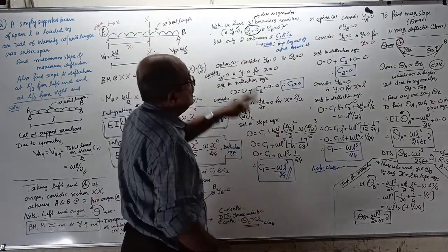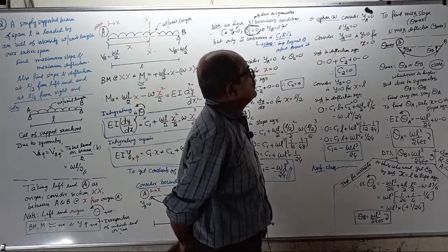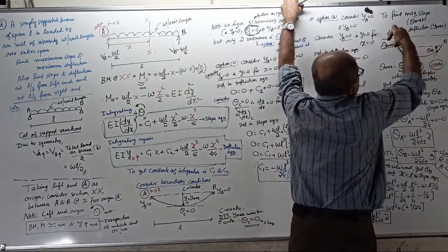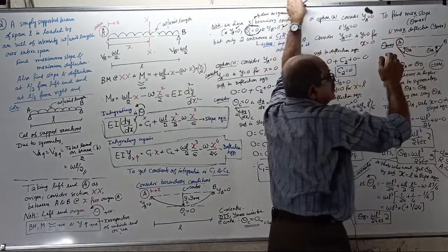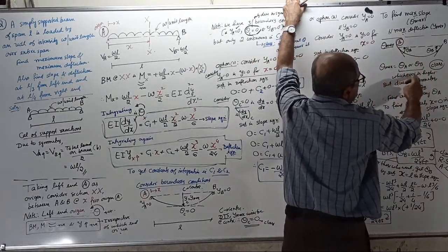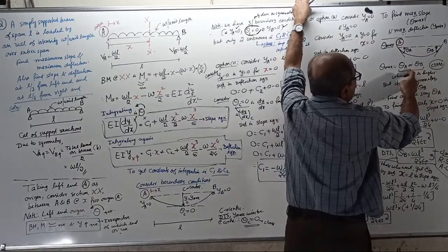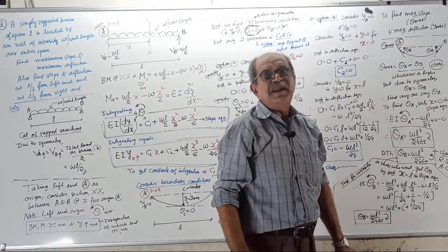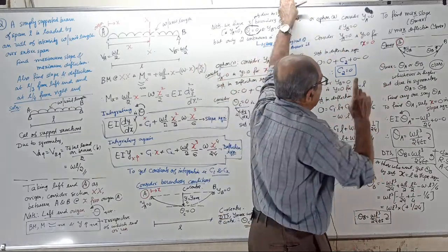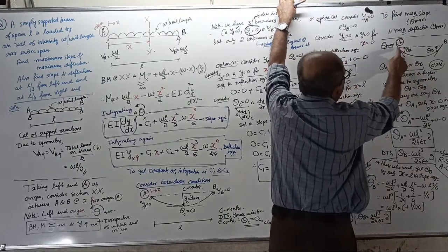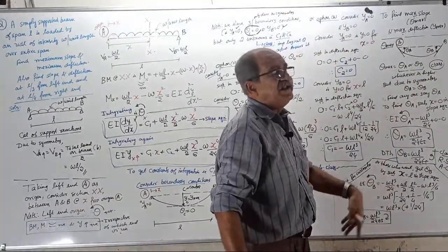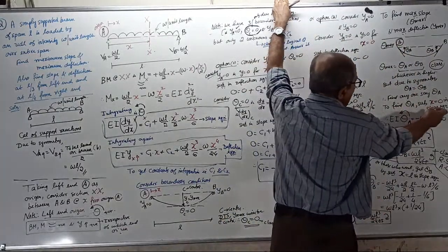Now, to find maximum slope and maximum deflection. See, a simply supported beam will bend like this. Maximum slope will be at the support. Slope means turning. So theta max equals theta A or theta B, whichever is higher. Class, this is irrespective of symmetry or unsymmetry. It is either maximum at A or at B. But here, due to symmetry, theta A equals theta B. Therefore, find any one of them, say theta A. Easy. Substitute x equal to 0.